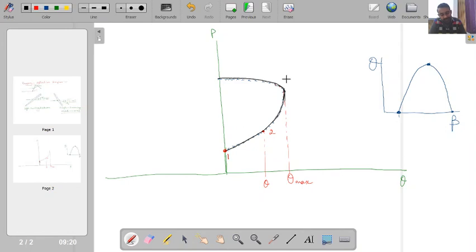In this entire range from 0 to theta max, this will happen particularly for the weak shock wave region, and for the strong shock wave region, from this point beyond theta max, we will get this type of variation. And this particular curve is for a Mach number of M1. The upstream Mach number for this entire curve was M1. This type of diagram is called a pressure deflection diagram, where I am fixing my inlet pressure condition and varying the different deflection angles to see the exit pressure points.